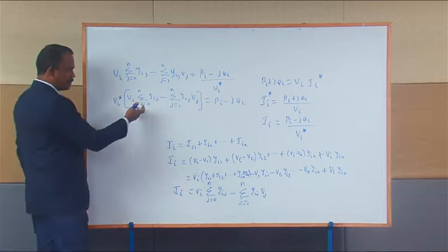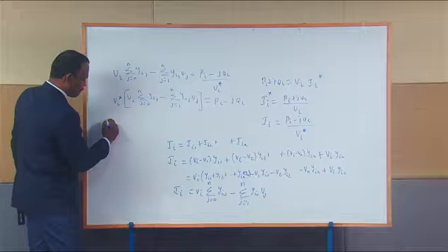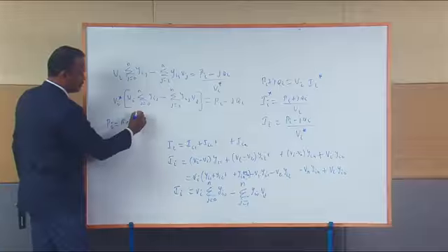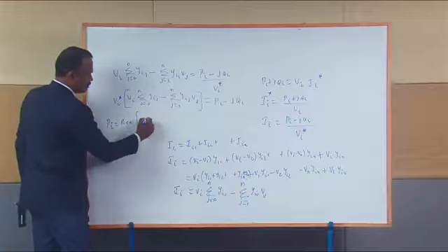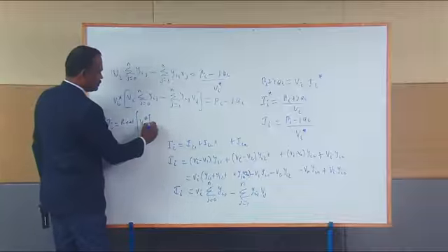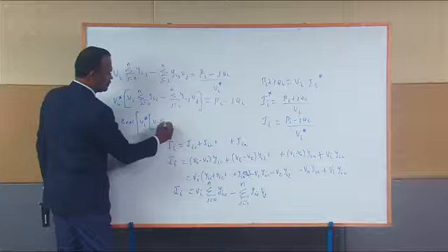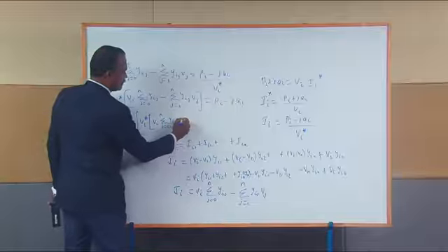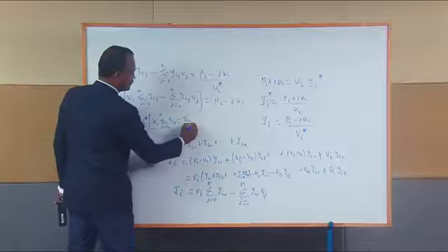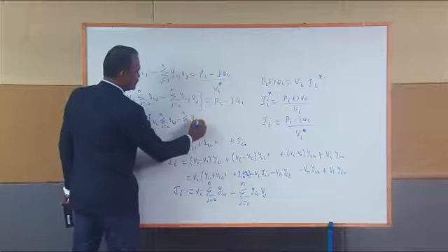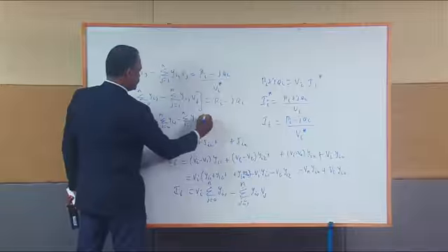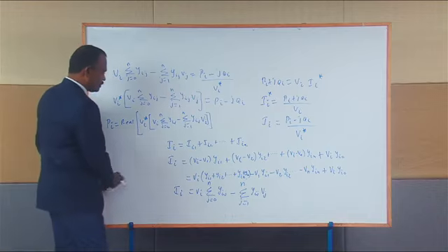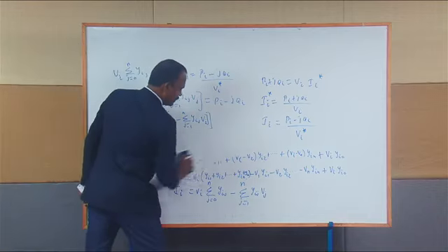From the above equation, I can write Pi is equal to real of Vi conjugate into Vi sigma j equal to 0 to n Yij minus sigma j equal to 1 to n Yij into Vj. I close this bracket. Okay. So this is the equation for the real power Pi.